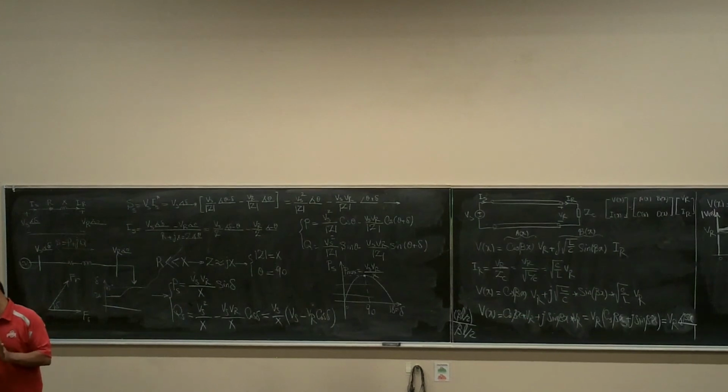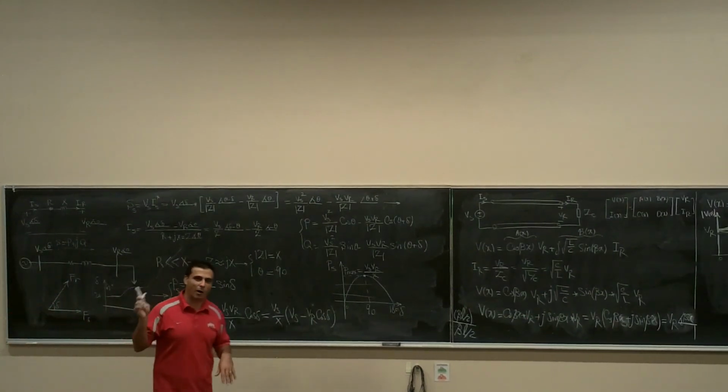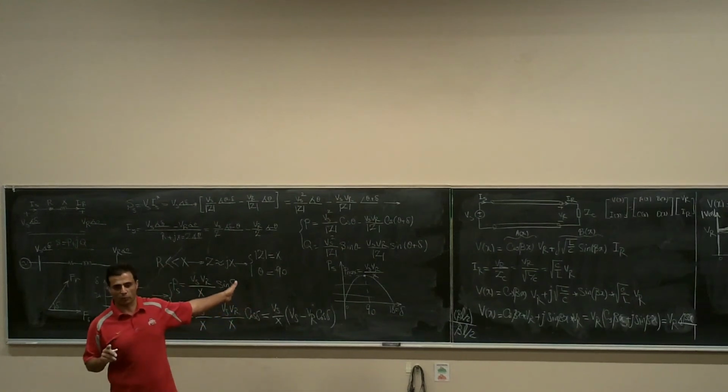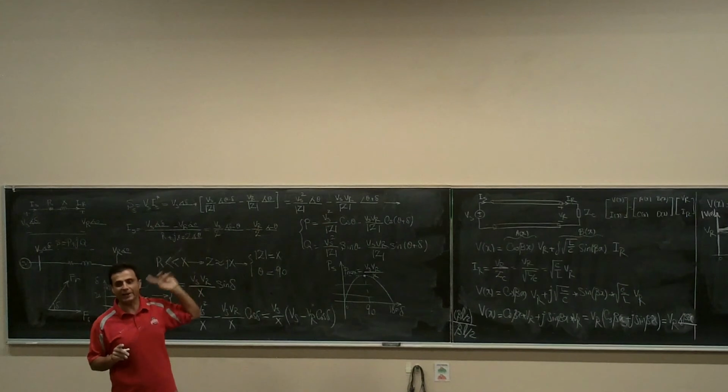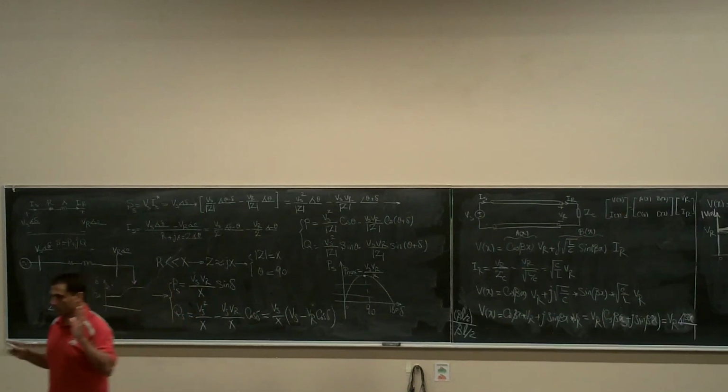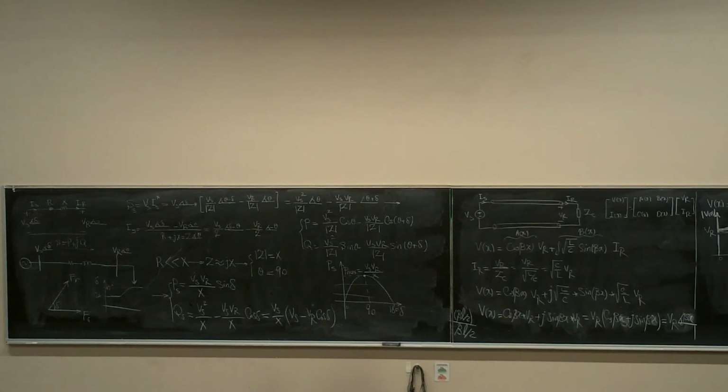Generator is much smaller. If you look at the ones in the power plants, they are lagging. They work with the lagging power factor. But those on the wind towers are leading power. They work with the leading power factor because it helps them reduce the size of the generator, make it much smaller. The smaller one is much easier to install up there on the top.